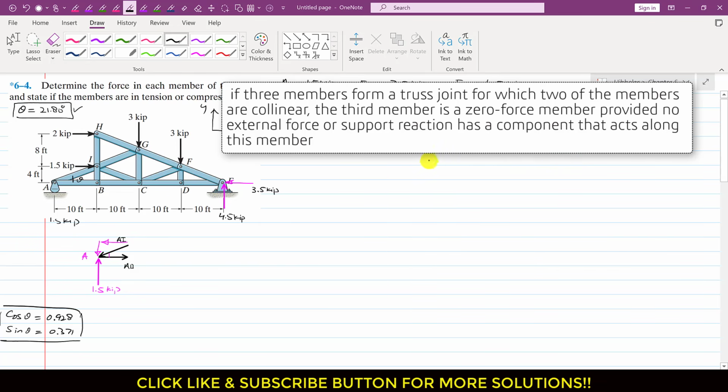Now after this we will consider joint E for equilibrium, right? So I will write joint E, since at joint E we have two known forces and two unknown forces. So now let's say that we draw the free body diagram. So at joint E we have this 3.5 kip force, right, which is acting in the negative x direction. So I will write this is 3.5, and we have this 4.5 kip force which is acting in this direction,